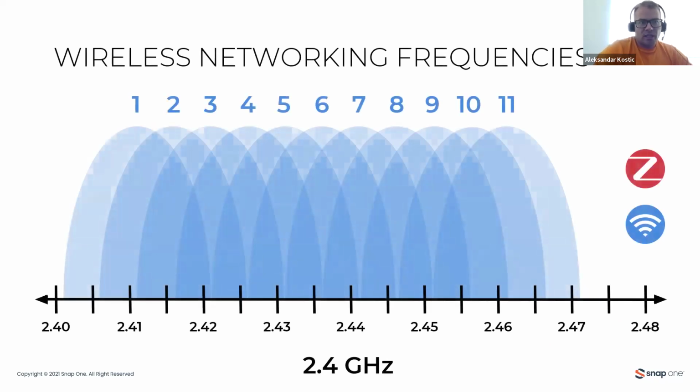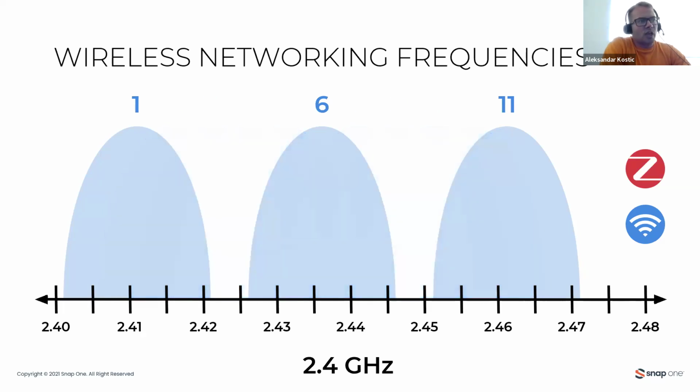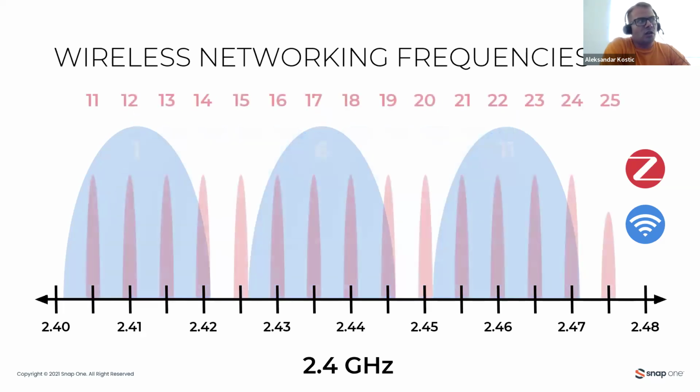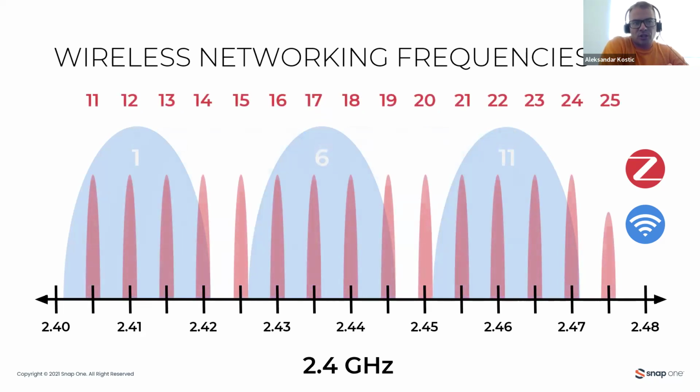The Zigbee protocol, as any other wireless protocol, relies significantly on clear channel communication, depending on the channel used to connect to the lighting controller. As Zigbee overlaps with Wi-Fi at 2.4 gigahertz, ideally we should use Zigbee channels which are not in use on the Wi-Fi, or Zigbee channels which are between the typically used channels on Wi-Fi.